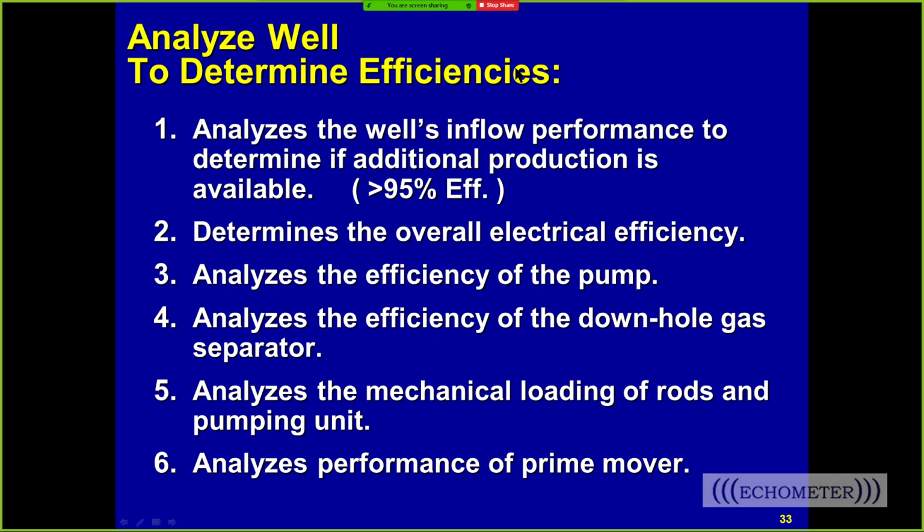So if you want to analyze to see if a well is efficiently produced, you're going to look at your inflow performance and your fluid level. You can measure the power and look at your overall efficiency based on your polished rod horsepower. You can see if your pump is full of liquid, which is important. A full pump is important for efficient operations. If your pump's not full, it's because there's a gas problem. You need a better gas separator to improve your efficiency.